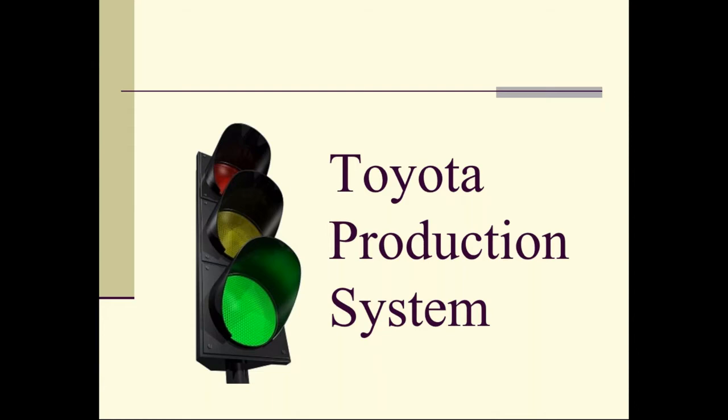And also the lights before that workstation will start to light up as well, because nobody wants piling up work in progress in incomplete inventory. If workstation 6 isn't using up materials fast enough, workstation 5 that's providing those materials will have to slow down, because they don't want a pile up of incomplete stuff showing up there. So they'll slow down, and the yellow lights will continue upstream as well. So a yellow light is infectious. It will propagate first downstream and then very quickly upstream, and it becomes an issue.